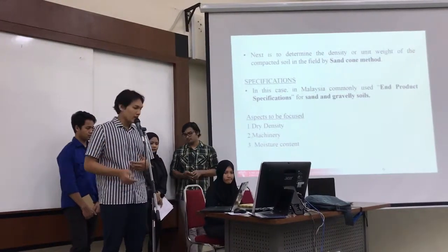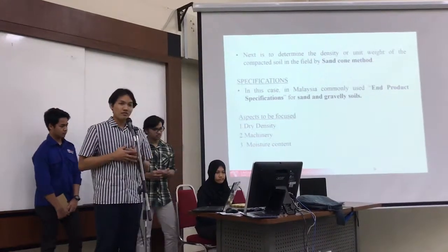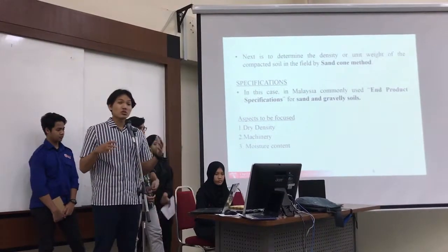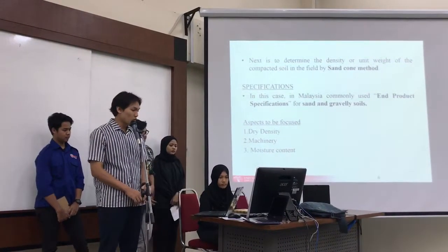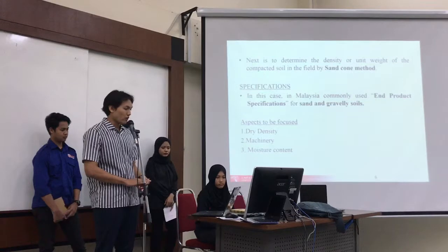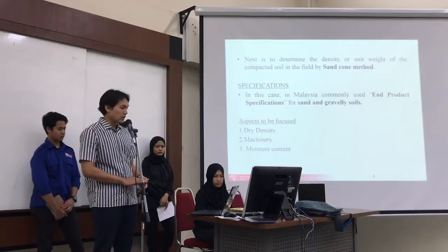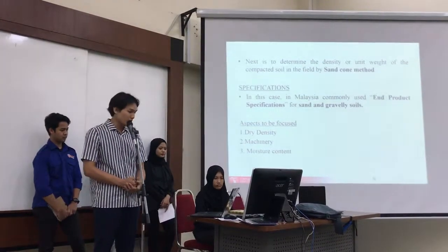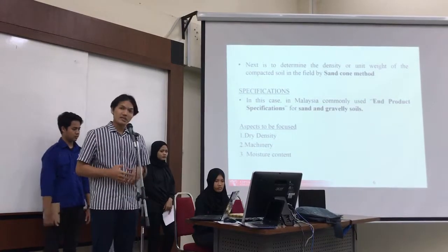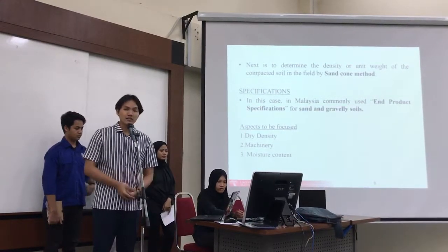If it's too wet, there will be a risk of excessive consolidation settlement and low strength. Therefore, it is necessary to facilitate compaction and achieve the required dry density.